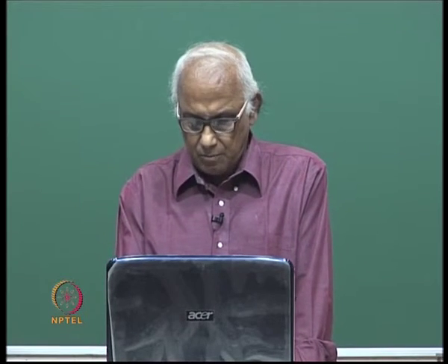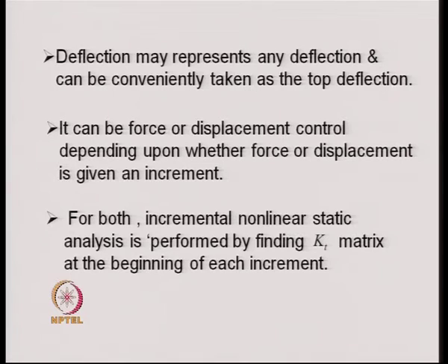Now, once we do that, the sum of the load gives us the base shear, and typically by load we mean the base shear in this case. The deflection may be represented by any deflection, however, it can be conveniently taken as the top deflection of the structure. So, the pushover analysis finally provides us a load deflection curve where load is the base shear and the deflection is the top displacement of the frame.